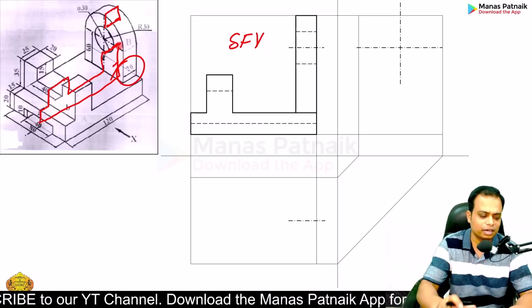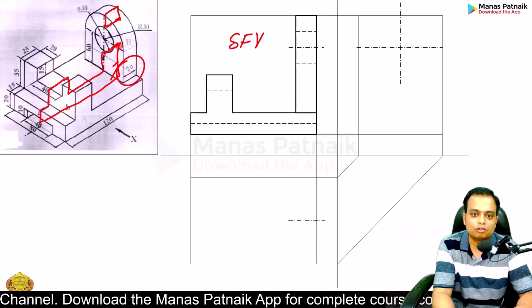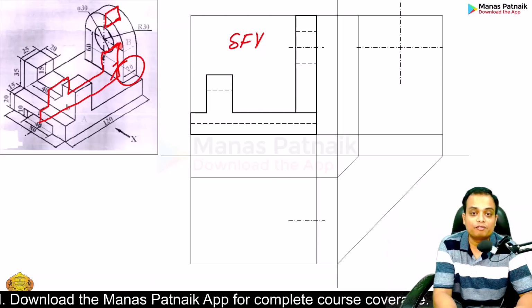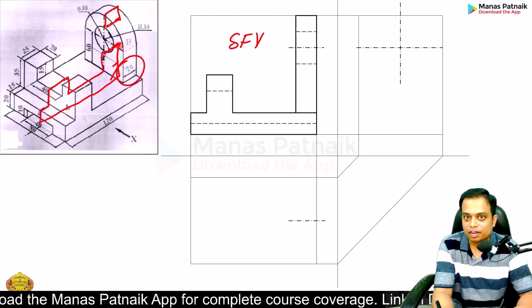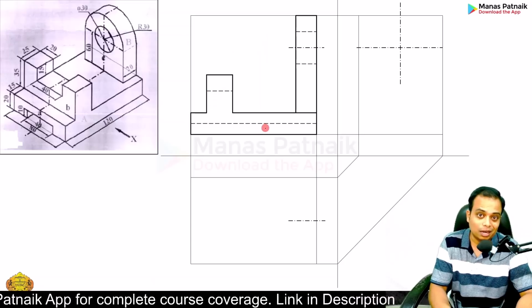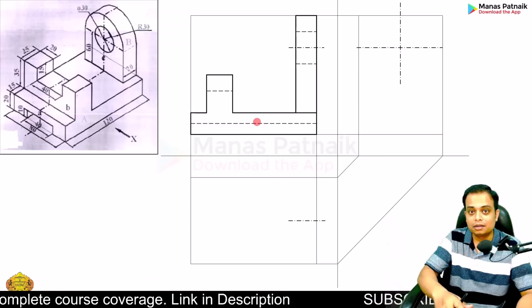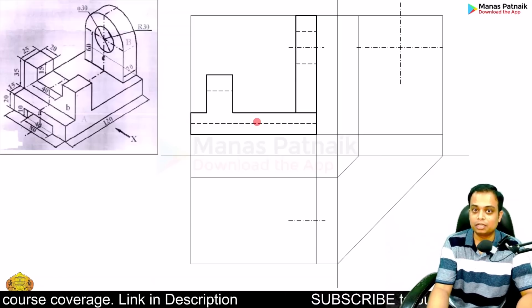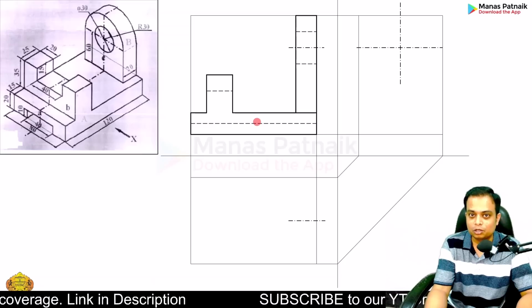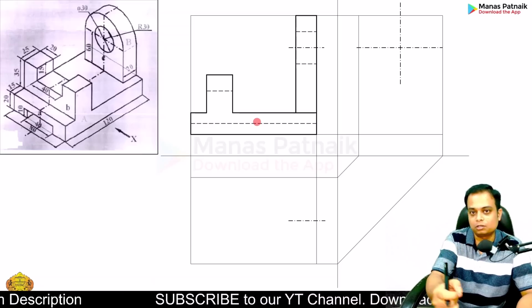We are going to work it out. Right now I have finished creating the front view, and I just want to show you how the hidden lines would look. And once you section the solid, how the hidden lines disappear, or rather, how the hidden lines are replaced by solid lines. This is the transition that I wish to showcase to all of you.